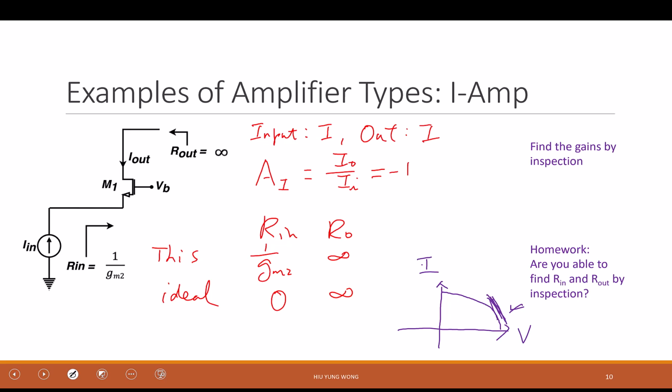But as mentioned, maybe we don't want to use the solar cell to output current, but to output voltage. Let's go back to photodiode. Let's just assume that it has small output impedance, right? Then you want to sense it. Then what happened? You have small output impedance, you cannot sense it well, as we said earlier, right? So you go through this transformation, then you have a large output impedance, then you can sense it well. Okay? So that's what I want to say about this. Any questions? So maybe I can say this is a current buffer.